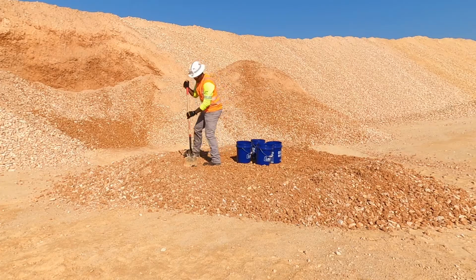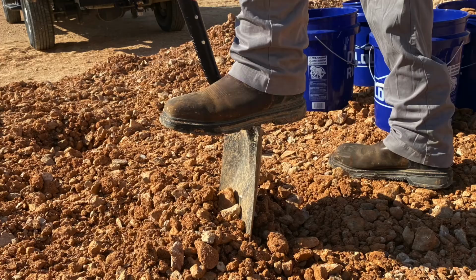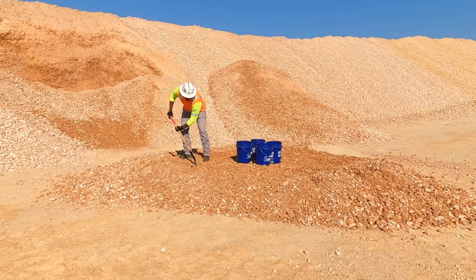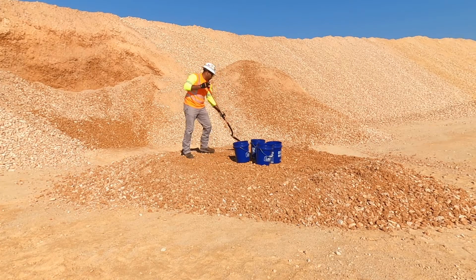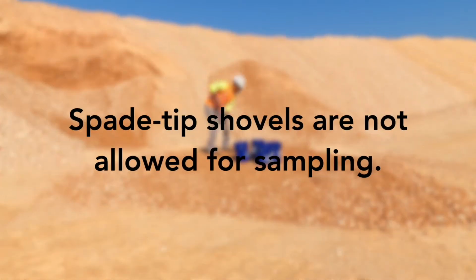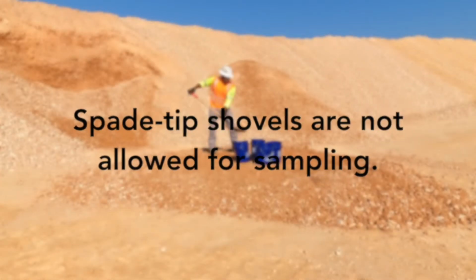Using a square tip shovel, fully insert the shovel as near as vertical as possible. Then slowly roll the shovel back and lift slowly so coarse aggregate does not roll off the sides of the shovel. Spade-tip shovels are not allowed for sampling flexible base stockpiles.